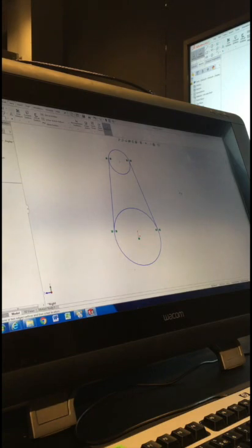All right. While you've got that dimension tool on, you can't sketch anything, okay? You have to click it up here or turn it off, all right? To be able to select things as well, you can't select things when it's on, all right? When the dimension tool's on, all you can do is dimension, that's it. We want a dimension between those two center points, all right? When you've got two circles, if you want a dimension between them, you can click on the exact center point, or you can just click the outsides of the circles, okay? It'll automatically go to the center point of the circle.